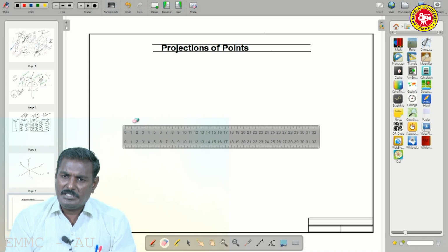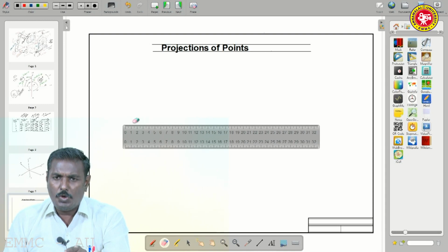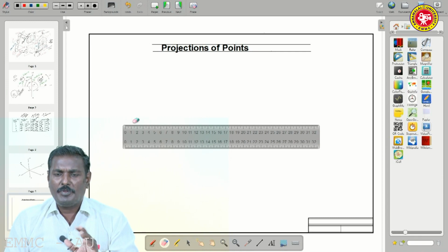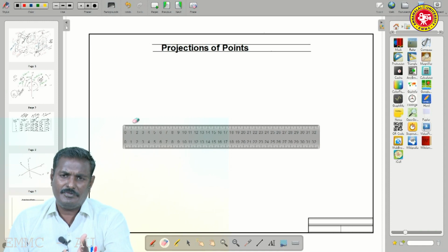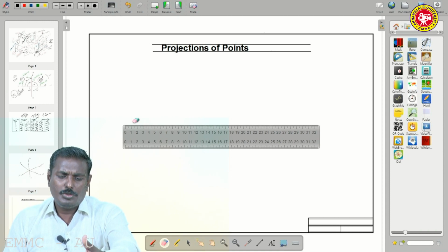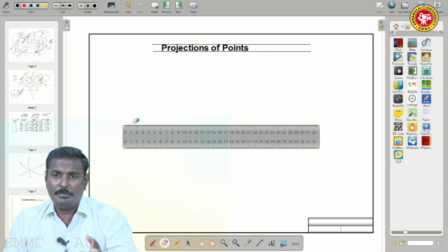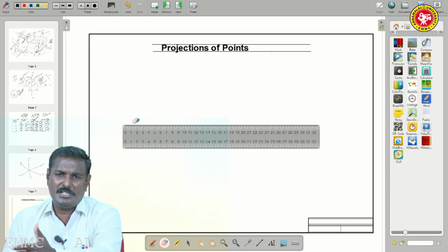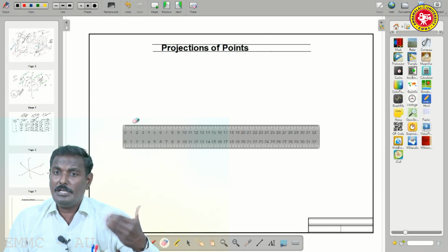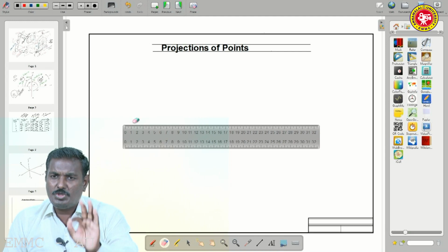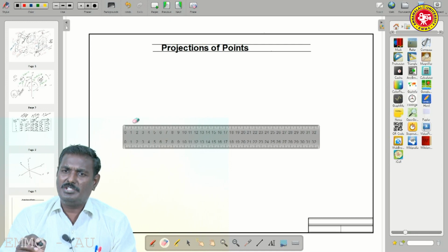Take a 2H pencil without pressing, very light, for that particular construction line or any imaginary line, visible only to your eyes at a very short distance. Your paper and your vision only should see it. If somebody else looks from some distance, say 0.5 meters, it is not very clear. That much thickness and darkness is enough initially.